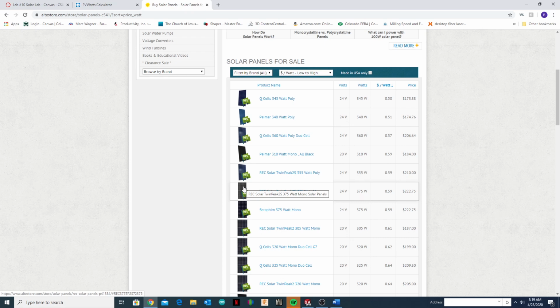We're always going to round up, okay? So we're going to get 21 panels that we would need if we were facing south, and to get our minimum of 10,200 AC watts using a 7 kW DC system, okay? So that's how I determine how many panels I need.